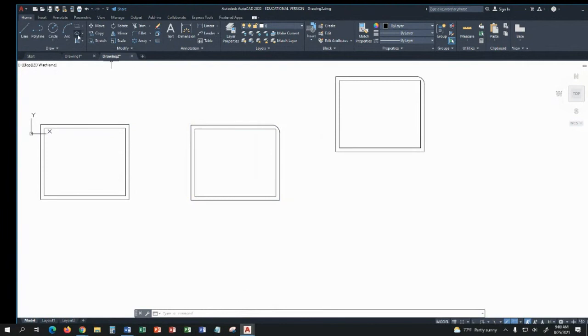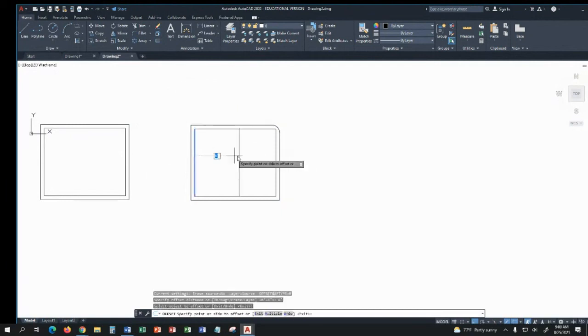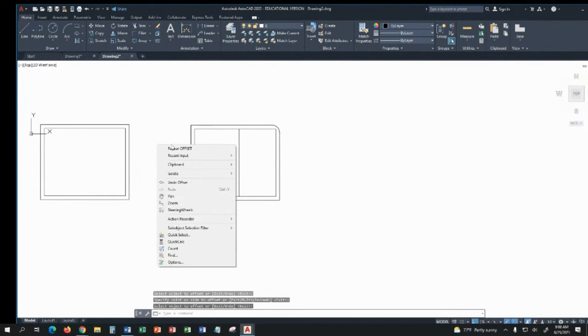I missed one step that I had asked you to do. So I'm gonna undo that. I asked you to offset one of the interior walls 6 feet. So here's our offset again. And I'm going to type 6, and this time I have to type feet, or it will think it's inches, and I've gone 6 feet over. And then I want to repeat offset, so I can just hit the return button, and see how it comes up, repeat offset.